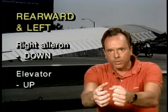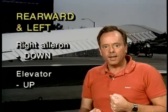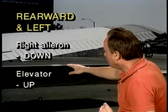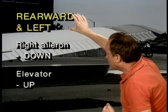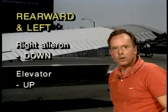And if you move the wheel back, that means you're trying to make the airplane climb, and that means the elevator will go up. So if you move the wheel or stick rearward and to the left, the right aileron is going to go down and the elevator will go up. Now, you might guess, will they ask you anything else about this? Yes, they're going to ask you what happens if you move the wheel forward and to the right.